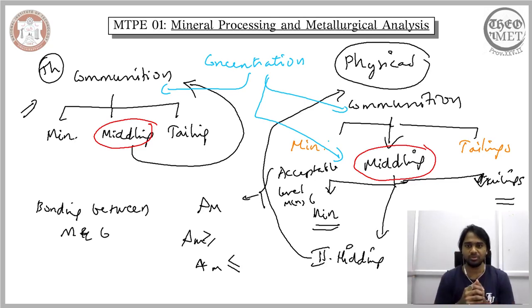When you introduce comminution to larger mined-out particles, you will get a mixture of both free particles and locked particles. When you separate out the mineral particles alone, you are essentially considering a subgroup of particles that possess a high concentration of the minerals, and that is what we refer to as concentration, the process of separating out the minerals from the mixture of free and locked particles. When we are able to separate the minerals out from the big mixture, all we will be left with is middlings and tailings, and we can modify the concentration process further in order to separate the middlings and tailings.